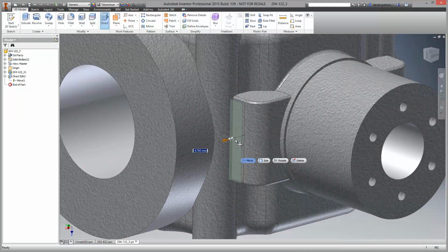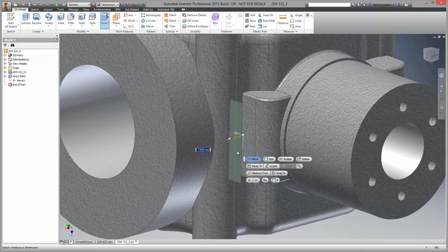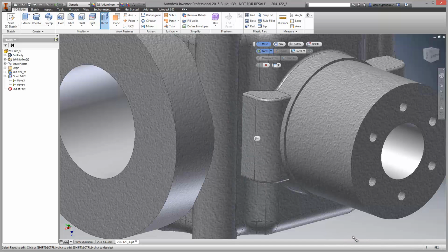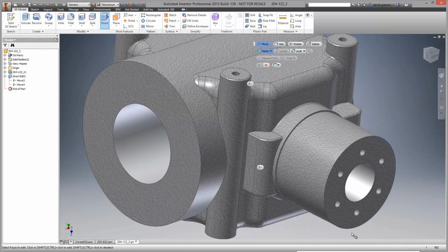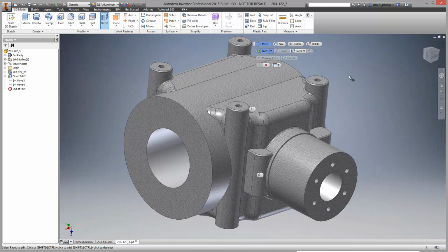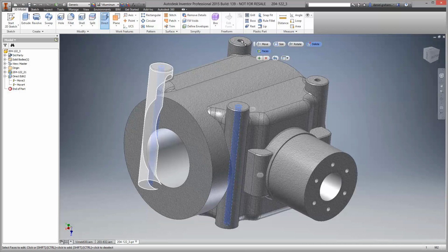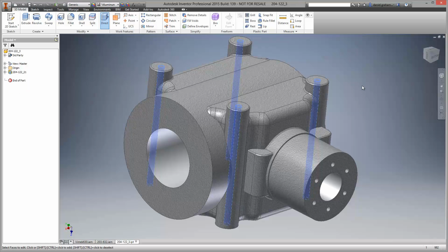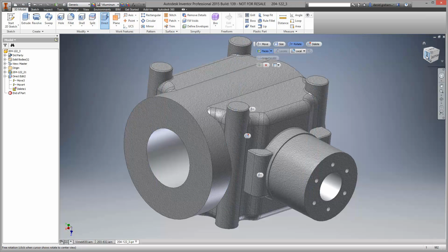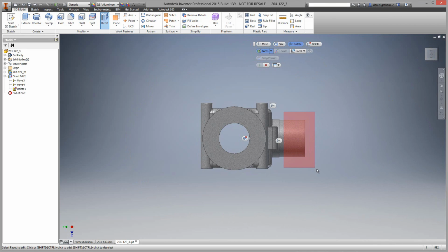You'll also notice that when we want to make a change to a group of faces here, we only had to select a single face, and the tangency conditions which exist on adjacent faces are maintained. We also have the ability of deleting existing geometry. So for example, if we wanted to put in bigger holes using actual hole features in Inventor instead of just changing the diameter of those 4 holes, we can just delete the existing ones and then put new holes in.